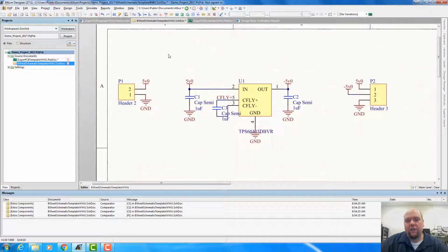For each component we have both the schematic symbol as well as the board footprint. So it's going to take the corresponding footprint for each of our schematic symbols and place that footprint in the board, and it's going to show the signal connections between the physical pins on the board side corresponding to the connections between the symbolic pins in the schematic side.